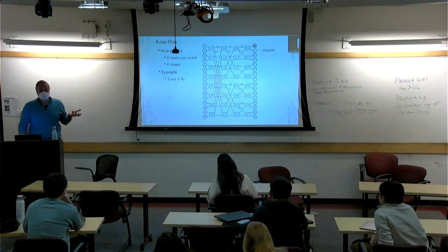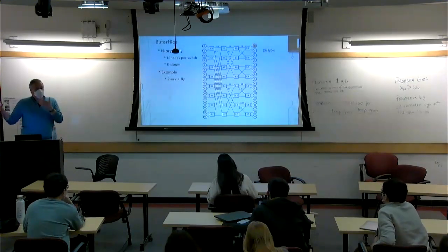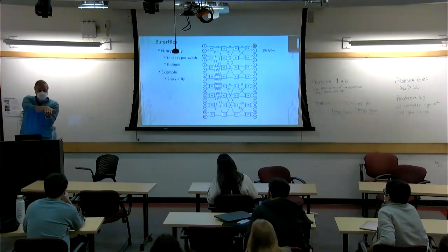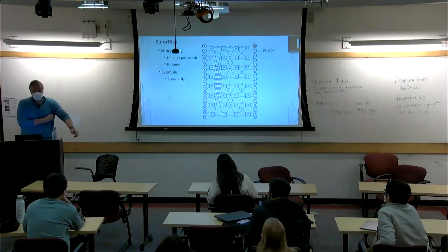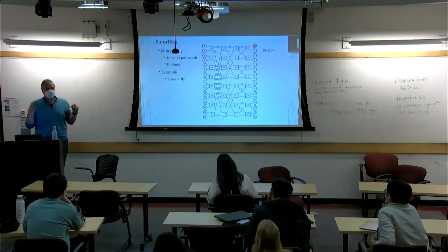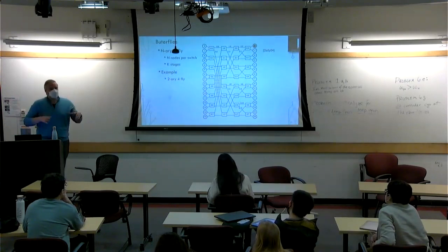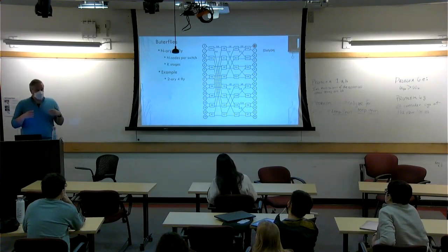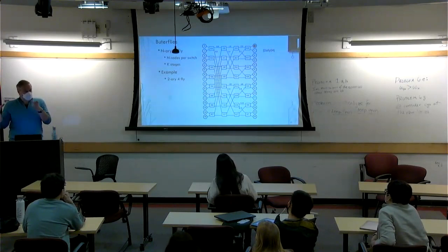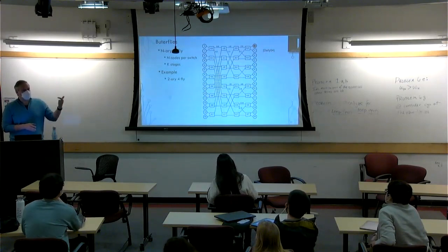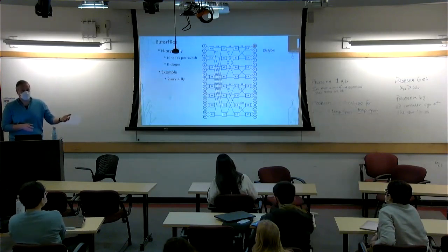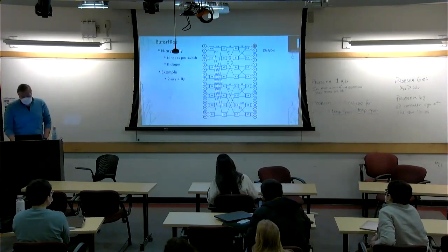That's processor 0. So this is kind of a logical representation. The physical representation is that this is folded, right? And so you have to think a little bit about that when you're floor planning your chip and mapping different types of networks. The same logical network topology can have many different floor plans on the chip, and each floor plan has impact on power, bandwidth, area, etc. I'll show you some examples of that too.